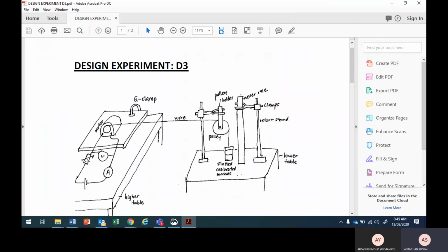Okay, you must have a variable resistor to make sure the current flow is constant. Because when you prolong connecting the motor, heat is generated, so the current will drop. The current drops, the input power is going to drop. We want to make the input power constant. I times V is your input power. So we must make sure the I is always the same. So we adjust the rheostat so that the current is always the same. That's why you need a variable resistor.